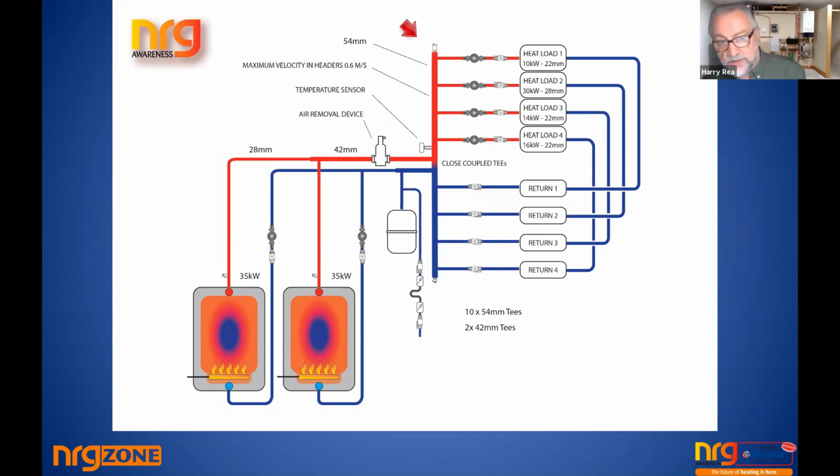So you deaerate the system, you get the water pump pressuring from the neutral point, or the neutral point is created by the open vent or the expansion tank. So you're pulling water through the boiler, maximum pressure in front of the pump, pushing through the correct size header, and then you're pushing off out onto the zones with the particular pump load.